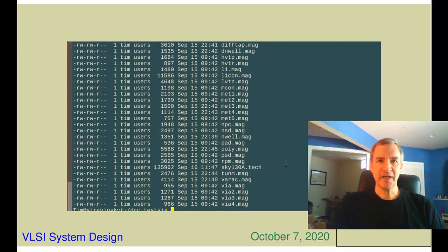First, make sure you're set up to view the layouts. This lab exercise is largely self-contained, so you don't need the complete infrastructure of files and tools around the Google SkyWater PDK. Since Magic has its own unique format, there isn't much that Magic needs from the SkyWater files. In fact, the Google SkyWater repository files are built with the help of Magic for extracting, generating views, and more. So it's necessary that the Magic tech file should be created first, as a lot of stuff depends on it. So its contents are largely independent of the repository contents.